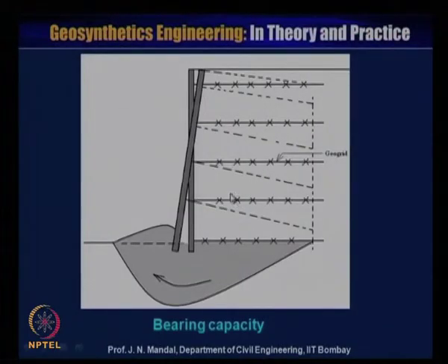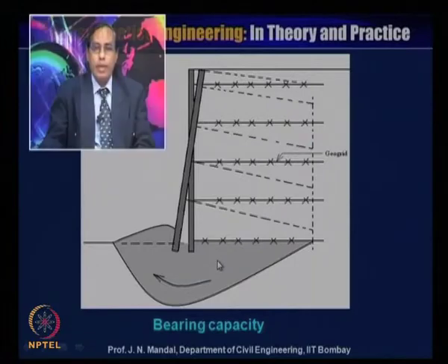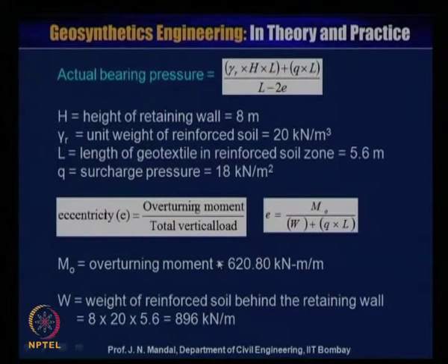Now, you can see this is the wall, this is the reinforcement, and there is a possibility for failure due to the bearing capacity. So, it is necessary to check the bearing capacity at this zone. If you want to check that bearing capacity, then what will be the actual bearing pressure?